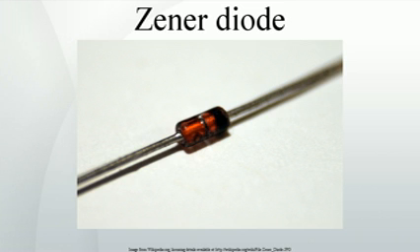Strictly speaking, a Zener diode is one in which the reverse breakdown is due to electron quantum tunneling under high electric field strength, the Zener effect. However, many diodes described as Zener diodes rely instead on avalanche breakdown as the mechanism. Both types are used, with the Zener effect predominating under 5.6 V and avalanche breakdown above. Common applications include providing a reference voltage for voltage regulators, or to protect other semiconductor devices from momentary voltage pulses.